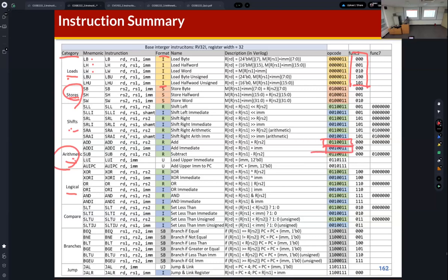And then R-type and I-type are different, right? So it's because the processor first needs to identify which format is used, to interpret which type of instruction it is. So that's why it's the same arithmetic instruction, add and add I, but the OP code is different.